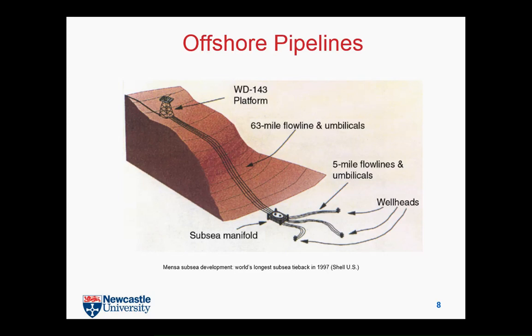And because from the seabed we usually have multi-phase flow, in a good case we should have oil and gas, but in most cases we also have water. So it means in the whole system we have 3 phases: oil, gas, and water. And gas is okay, oil is okay, but actually we don't need water, right? So imagine that if we have a pipeline as long as 100 kilometers and you transport some water from the deep sea to floating systems, you are wasting a lot of power, right?